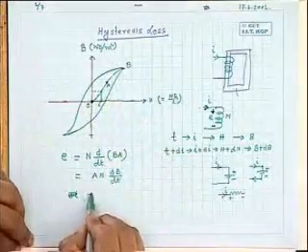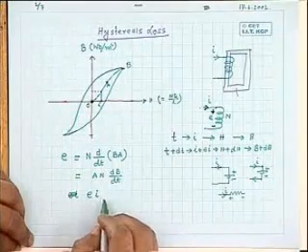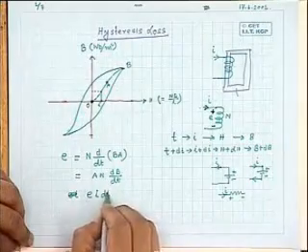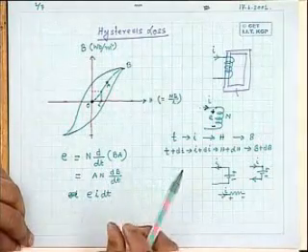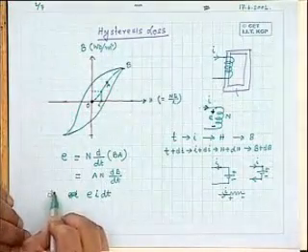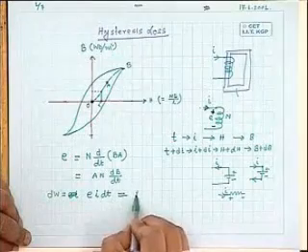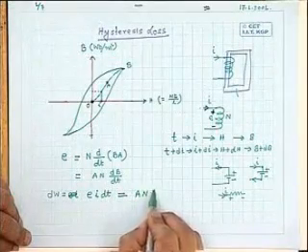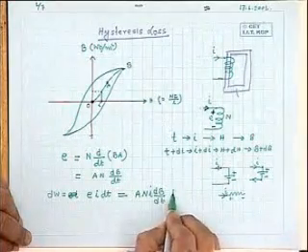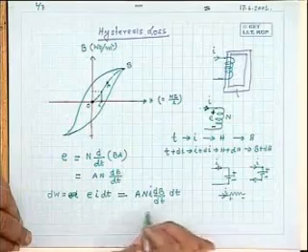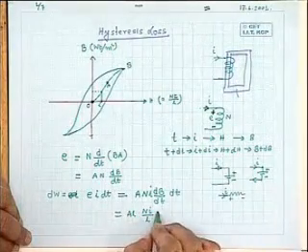Therefore from 0 to B, the power delivered to the circuit is EI, and in time dt how much energy has been given to the coil? This into dt. Energy supplied to the coil over time dt is the voltage at that time, the current at that time, into the time. So this is the amount of energy supplied to the coil. Now you substitute the value of E, which is AN dB by dt, into I, into dt, which can be written as A into L into Ni by L into dB.